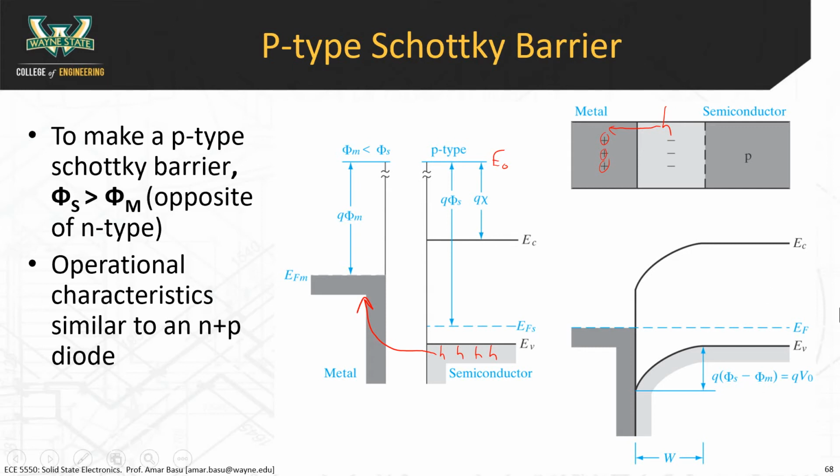And you can see this in the band diagram. The way that you can see it in the band diagram, I'll describe to you another thing that's a useful way of thinking about the band diagram. If you look at out here, the distance between EF and EV is small. What does that tell you about the hole concentration? There's a lot in the valence band. Yes. The closer EF is to EV, the more holes you have in the valence band, right?